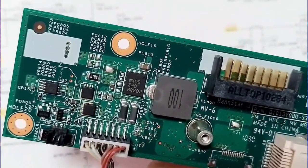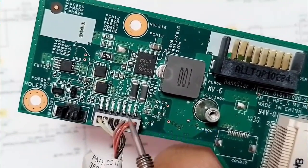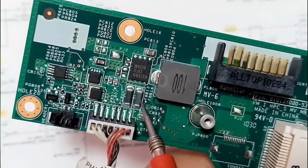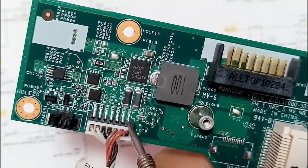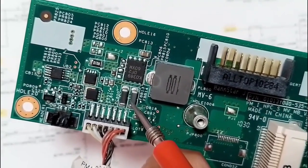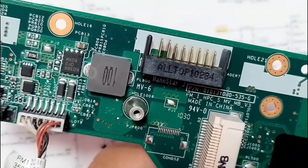So basically over here we have the charge circuit, or the DC battery charger, where we have, as you can see, the power jack cable. Okay, so as you can see here we have two power MOSFETs. As you can see over here we have two inductors. Basically these two inductors are connected directly to 19 volts. Here we have this red cable means 19 volt. So two inductors, we should basically find here 19 volts. Okay, we have here another MOSFET, we have inductor, and over here we have the battery connector.